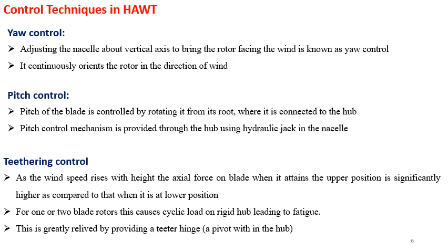Wind speed variation control. Wind speed variability must be considered, especially in the design of larger wind energy conversion mechanisms. For a given turbine, there is a minimum wind speed called the cut-in speed, at which rotation is allowed to start. Then there is the rated wind speed, at which the generator produces its rated power, and the rotation rate is maintained constant by varying the output of the generator.